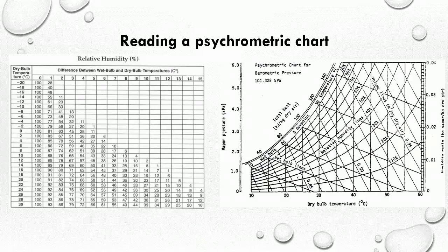To determine the relative humidity from your dry and wet bulb temperature readings, we can use a psychrometric chart. A psychrometric chart provides a graphical representation of the thermodynamic state of air at a given atmospheric pressure. In meteorology or air conditioning, the reference pressure is typically pressure at mean sea level. Knowing any two state variables of interest, we are able to determine the other variables. A psychrometric chart typically has lines corresponding to dry bulb temperature, wet bulb temperature, enthalpy, relative humidity, and the humidity mixing ratio.